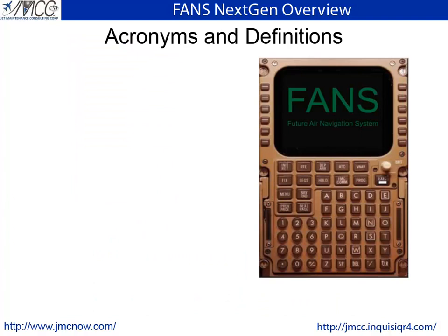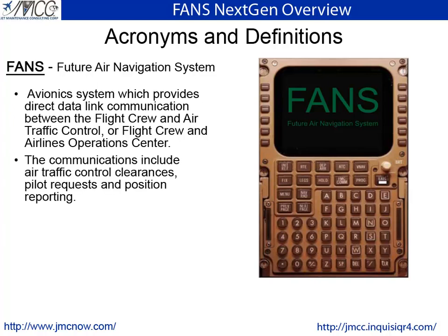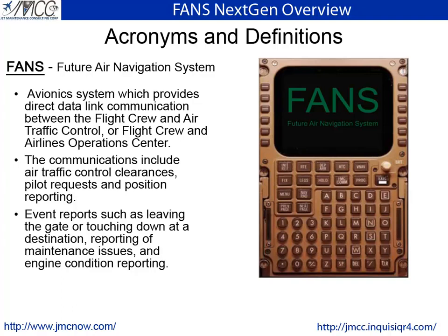In order to proceed with this course, there are a few acronyms and definitions that you need to understand. The first of these is FANS. FANS is an acronym for Future Air Navigation System. FANS consist of avionics systems which provide direct data link communication between the flight crew and air traffic control, as well as the flight crew and the airline operations center. The communications include air traffic control clearances, pilot requests, and position reporting. It can also include event reports, such as leaving the gate or touching down at a destination, reporting of maintenance issues, and engine condition reporting.